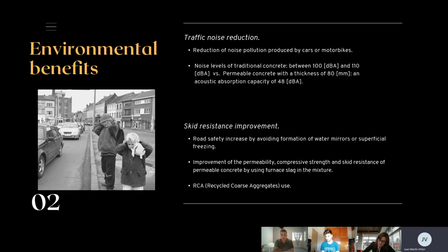The skid resistance is a factor that should be considered for designing parking lots, roads, or sidewalks, as it improves their safety by avoiding the formation of water mirrors or surface racing that cause accidents, errors in route planning, and operational interruptions. In addition, the research showed that blast furnace slag improves the performance of these benefits, increasing its permeability, compressive strength, and slip resistance, making the application surface more efficient.